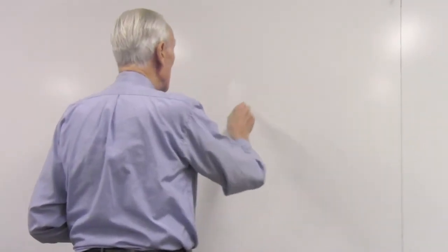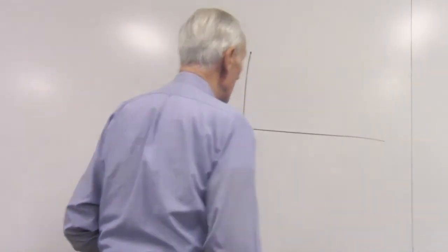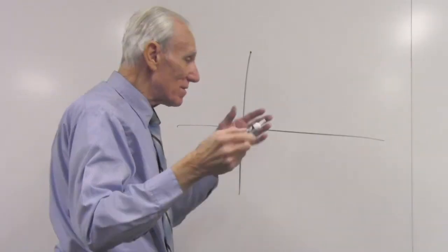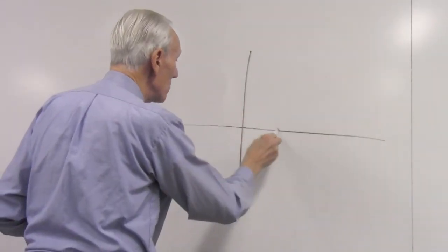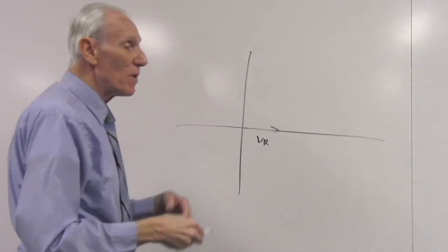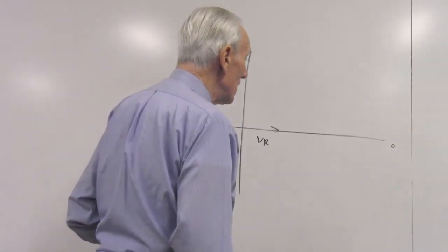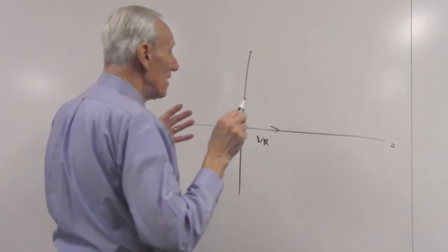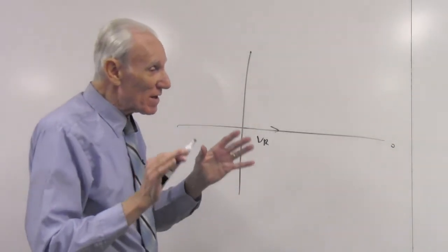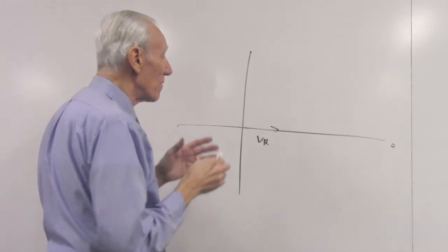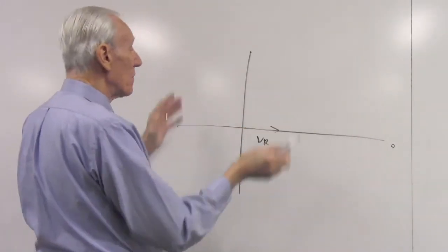So in part C we have our phase diagram, and of course, just to make sure you get the same answer, you measure the voltage across the resistor, and it's plotted at the 0 degrees phase angle. And then you add to that like vectors, because these voltage phasors add mathematically like vectors.